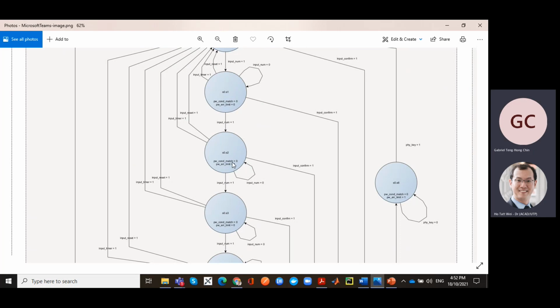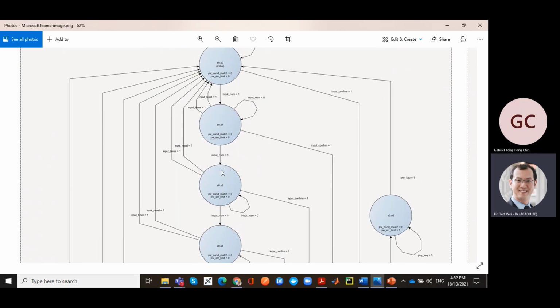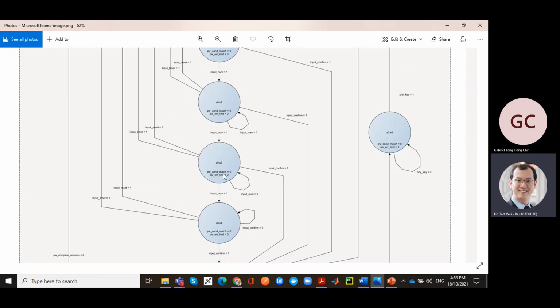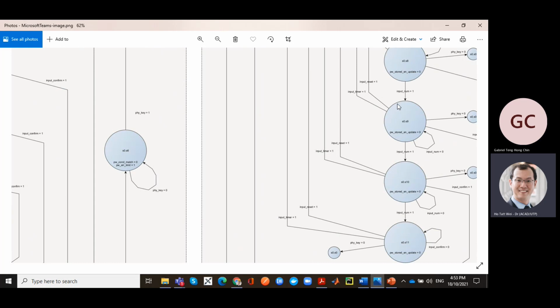But what I'm saying is that in this particular circuit or implementation, it is not defined where you are storing the key. With this kind of architecture, it looks like you're setting yourself up for a shift register. So you have the input num going here, but the number of the key is going to go into a shift register. There's going to be a parallel flip-flop chain here. The key number goes in, and on the next clock the next input num propagates down the shift register. So at the end of 5 button presses, you've got the 5 numbers in the shift register. You can then use an equalizer to compare with the actual password.